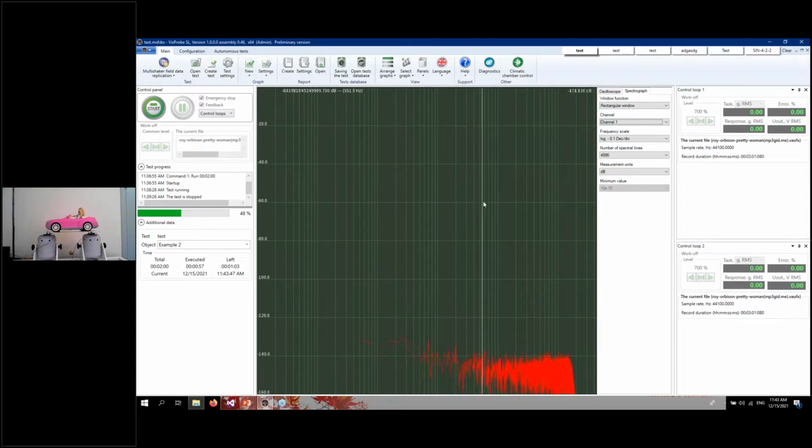It is very useful when you're experiencing some problems with the test startup, and you can open the oscilloscope and see if you have, for example, a 50 Hz disturbance, and if you have it, you can try to put a wire between the shaker and the controller, and resolve some ground issue and see if your action helps.